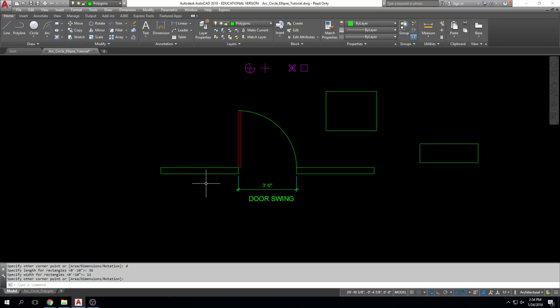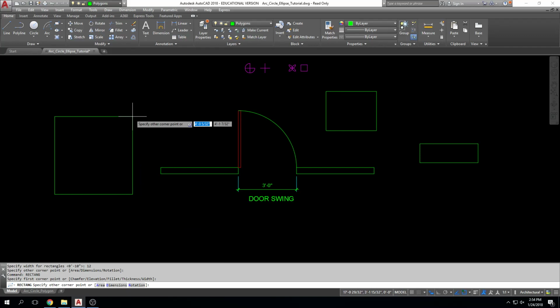The final way is probably the most used case of relative coordinates that I use. When I'm drawing rectangles specifically, I use a coordinate system quite frequently. Back in the day, before we had the option to choose dimensions, let me start the rectangle command, the only way that you could define a rectangle was using a relative coordinate where you type @24,24, enter, right?